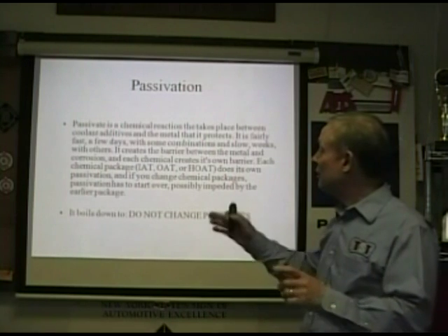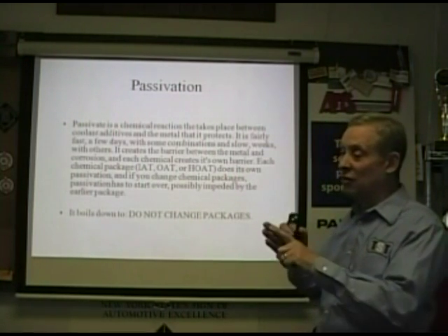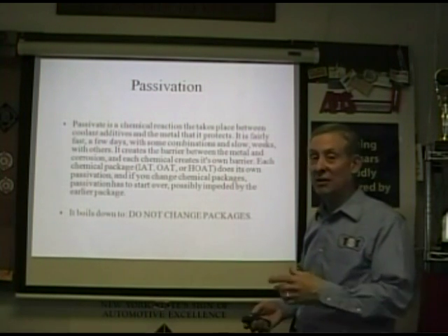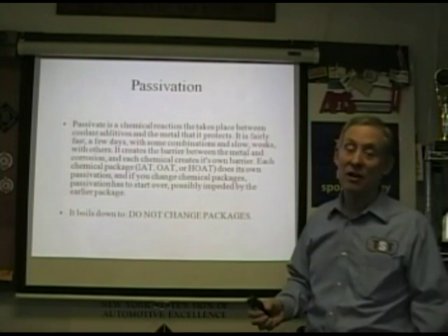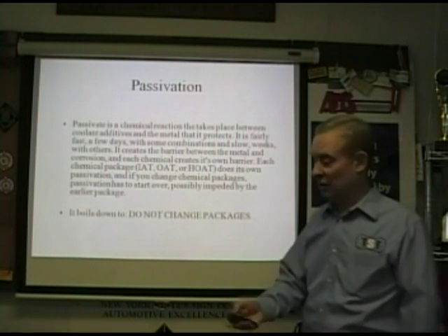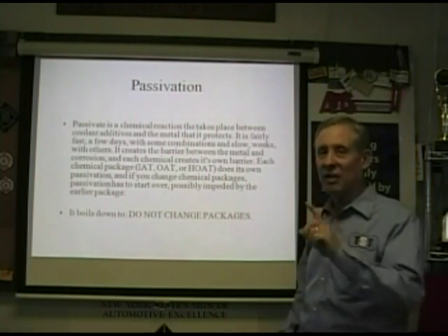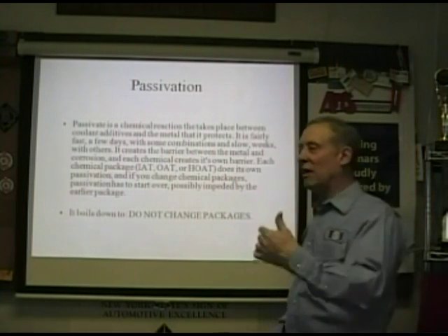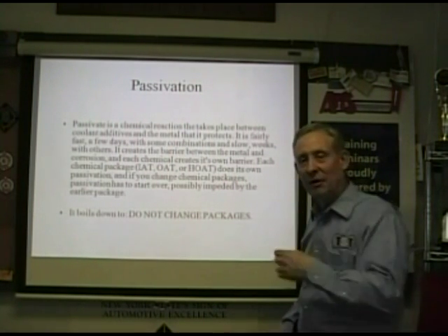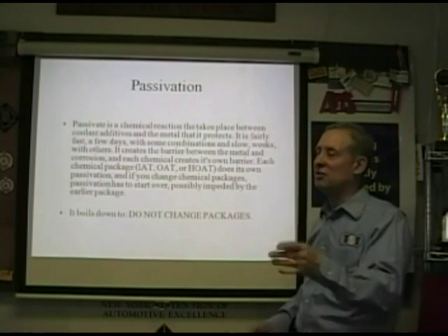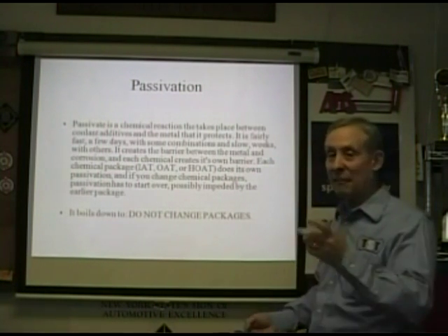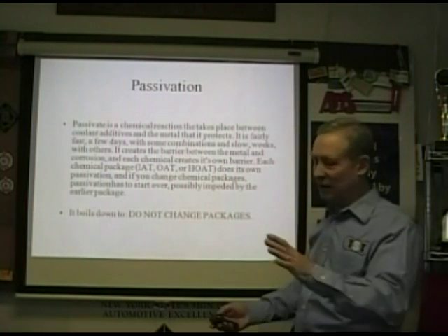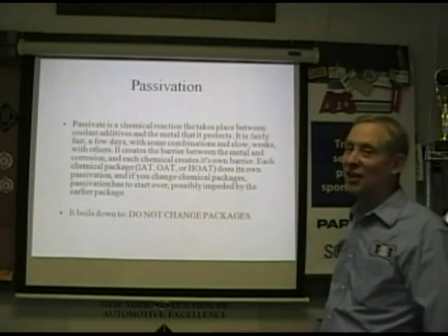Different chemistries, even maybe in the same manufacturer, from one date to another. They make changes in their coolants, and that changes the passivization, and they're not compatible with each other. Again, what you really have to know is don't mix the stuff, flush the car, put the right stuff in. This process doesn't happen in a second. It's a chemical process that occurs as the vehicle is driven, but it happens quickly after it's changed. Again, don't change packages. Flush it out. Same thing, I say it over and over again.